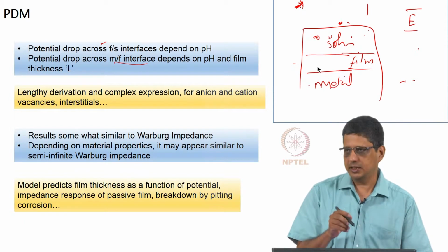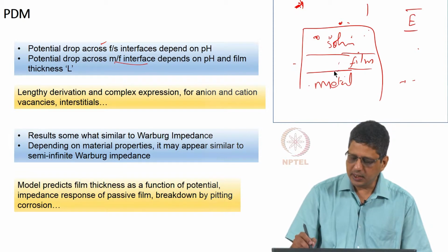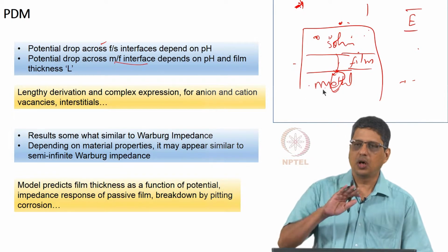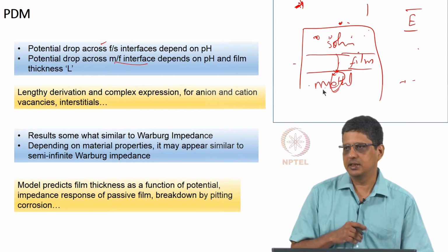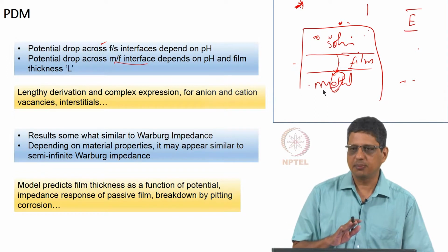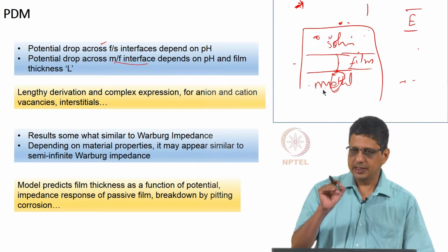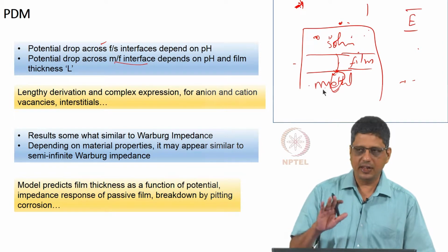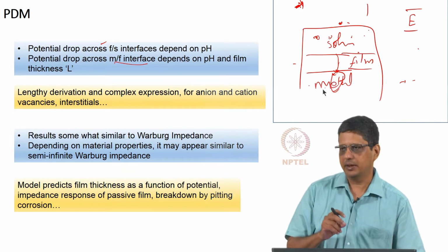Of course, it is dangerous because it is attacking the material and it typically goes below and keeps corroding more. So, on the surface you will see a few points, some corrosion, but actually corrosion can occur deeper. If you see full corrosion everywhere, it is not such a problem, meaning it is a problem, but you are prepared for that. If you see rust everywhere, you know it is getting weaker. If it is a few pits, you think everything is okay unless you look very carefully. It looks like the surface is okay, but actually the material is getting weakened.